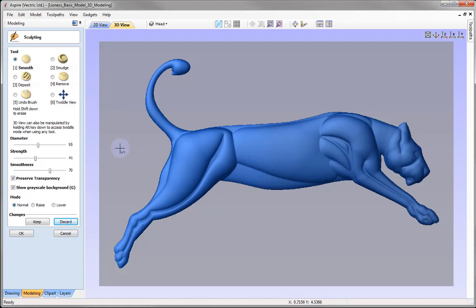So to activate it, we simply press the left mouse button down. You'll see now it's changed colour, it's now red, it's telling me that we have now activated the smooth tool. And so if I come over to my model, still holding the left mouse button down, you'll notice now that we're actually blending or smoothing material together. I'm just going back and forth, and that will just smooth that out. And sculpting will only have an effect when clicking the mouse and moving it. So you could think of this action being similar to using sandpaper.